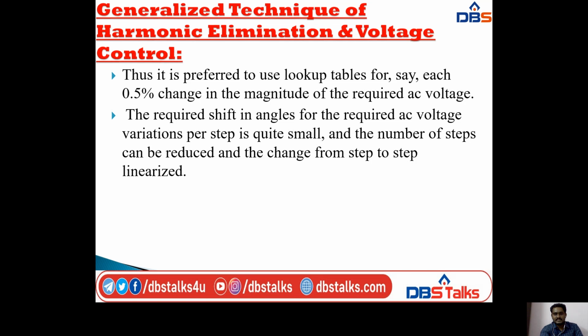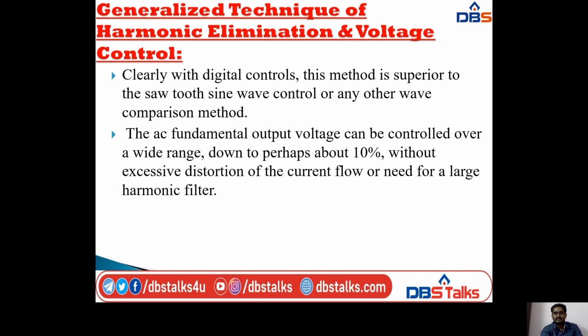So these are the generalized techniques of harmonic elimination and voltage control, and we have a few more points to discuss. Clearly, with digital controls, this method is superior to the sawtooth sine wave control or any other wave comparison method. That is with digital controls only, not manual or analog controls.